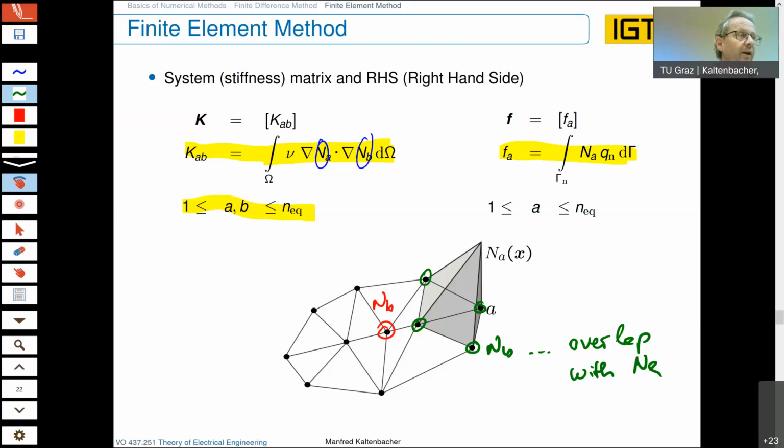That doesn't depend on the method, it depends on your partial differential equation. There are also partial differential equations, not the weak form, the strong form, where you have, for example, a convective term, and they will be inherently non-symmetric. Here we get the symmetric sparse matrix. So we even can reduce, and that is important if you have 10 million, 20, 30 million unknowns. That's standard in computation. It makes a difference if you store all the non-zero entries or just the diagonal and the non-zero entries above the diagonal.